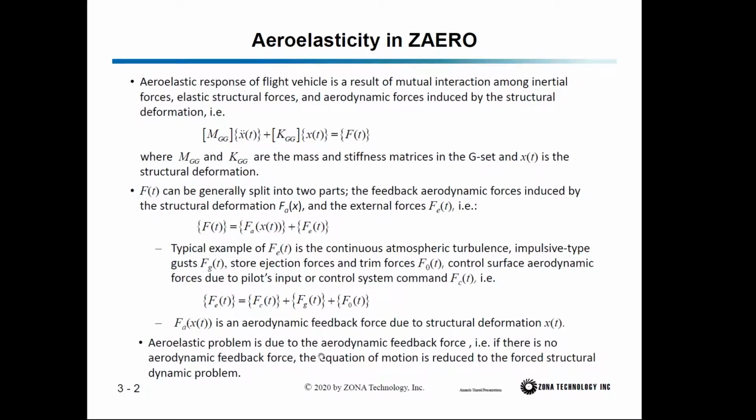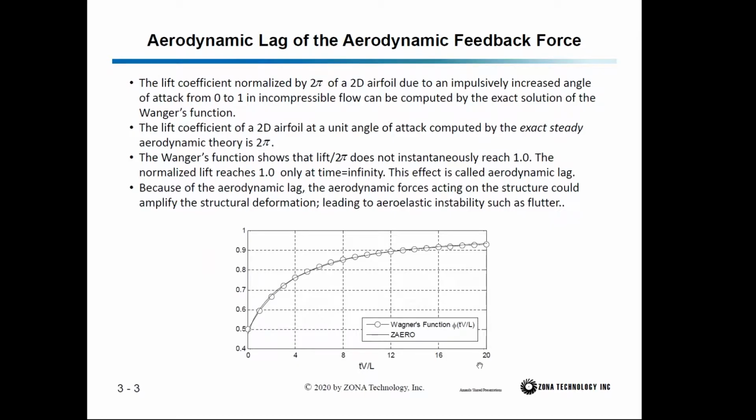Aeroelastic problem is due to the aerodynamic feedback force. If there's no aerodynamic feedback force, the equation of motion is reduced to the pure structural dynamic problem, and therefore for the pure structural dynamic problem, there's no instability problem. When the structure deforms, it can induce aerodynamic forces, but these forces do not react instantaneously. Rather, there is an aerodynamic lag effect.